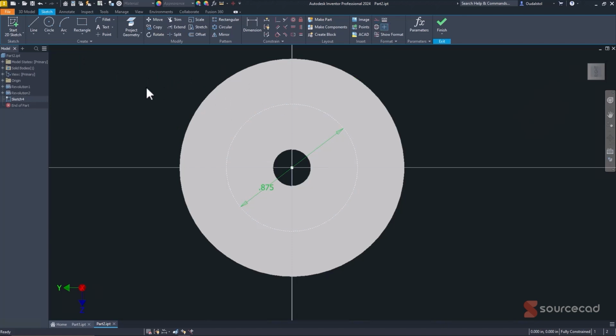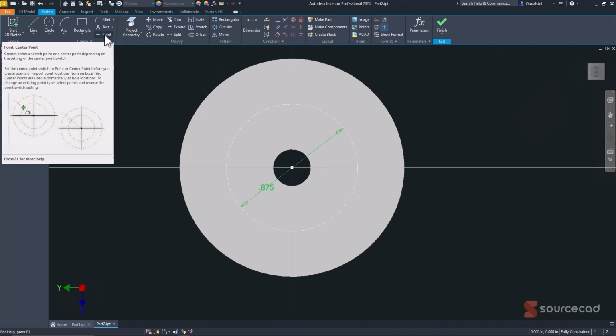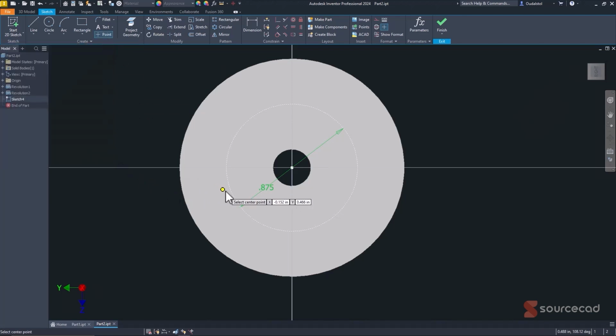I want to make it very clear to myself and people coming behind me, this is here to help me do something. So what I'm going to do right now is this point, and I'm just going to place one. I'm going to do one at the bottom and one right here. So I got 3 points, and what I can do is actually again use this horizontal constraint. Again, it's a little odd. Why am I doing horizontal? But just pay attention to the purple line.